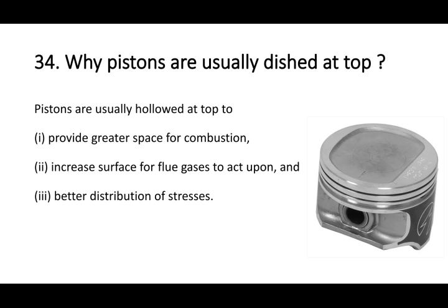Next question. Why are pistons usually dished at the top? So here you can see the dish piston, right? The pistons are usually hollowed at the top to provide greater space for the combustion. So with such design, we can provide more space for the combustion, increase the surface for flue gases to act upon. Again, we can increase the surface area, then better distribution of stresses. So as we increase the area, again the stress will be distributed properly.